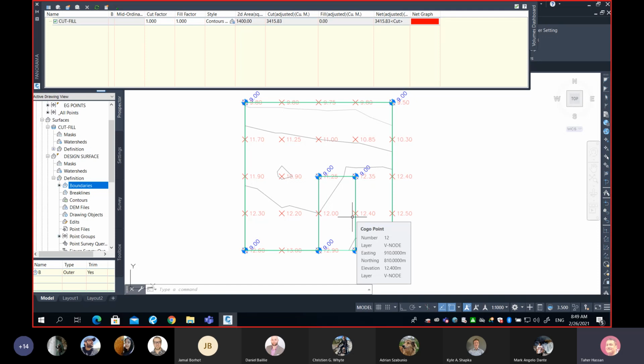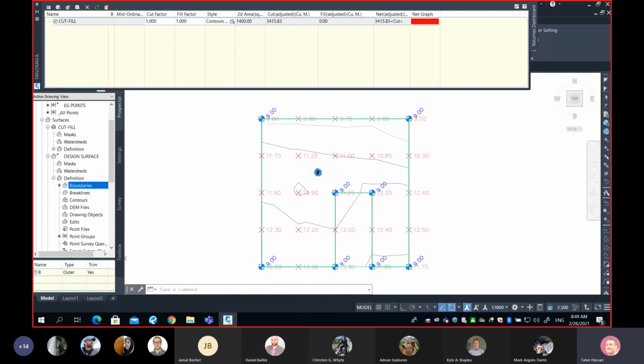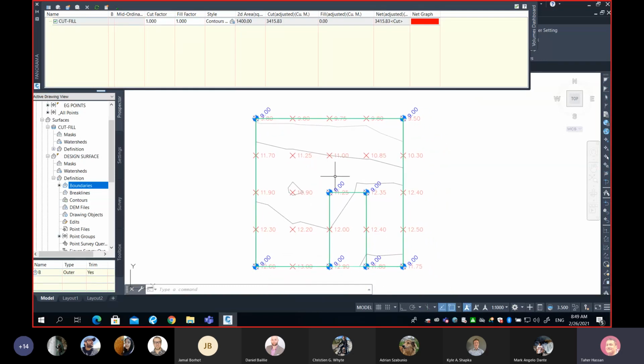Anyway, I'll give you the answer. The triangular shape will give you a better answer simply because it's a better representation of the ground. It doesn't assume a perfectly flat surface between the 4 points, but rather breaks at one of the diagonals. So it's a much better representation, and it gives you a better volume.